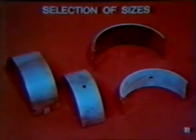Both main and connecting rod bearings come in a selection of sizes, so they can be fitted for a close to ideal clearance when the engine is built up. This clearance allows for normal bearing wear without a loss of oil pressure.